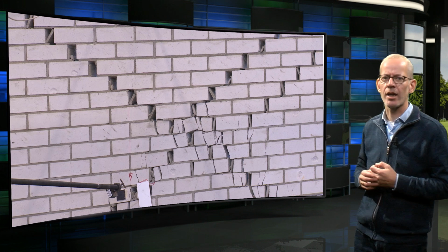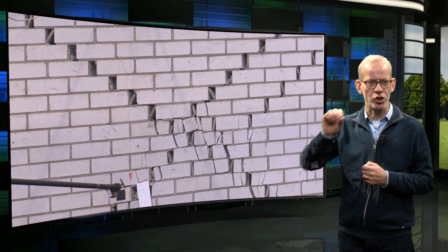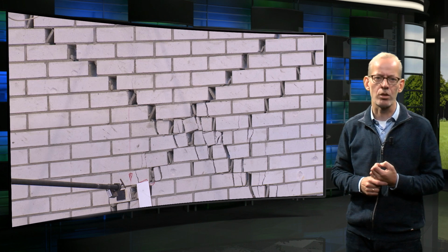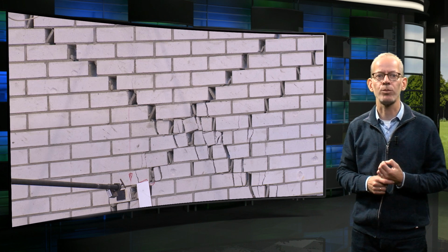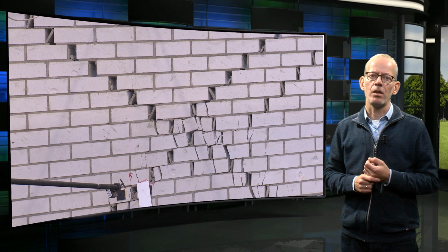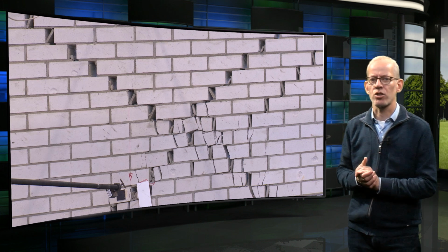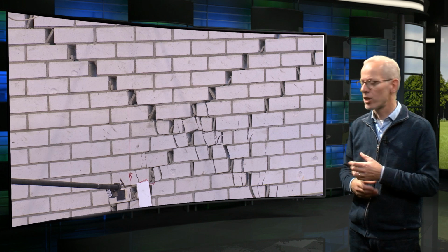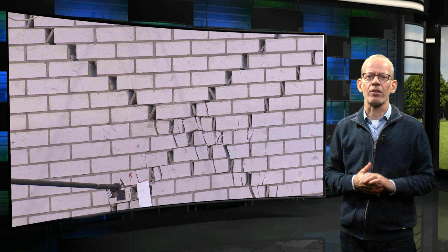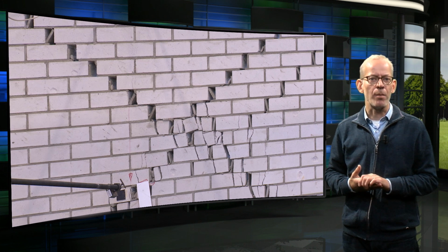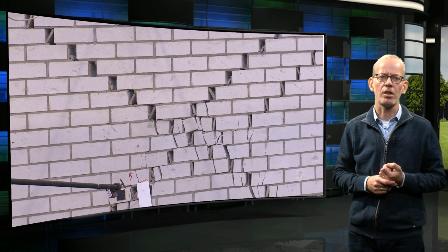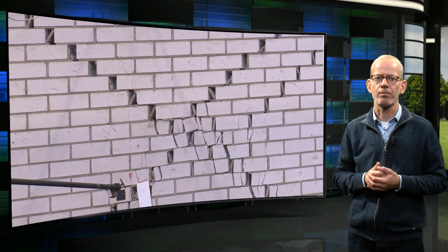You can clearly recognize here the two diagonally shaped series of cracks going from both the top left to the lower right and from the top right to the lower left. If you examine one of the cracks in more detail, you can see that the head joint has opened while the bed joint is still connected. At the same time, however, a clear horizontal shift is visible between the bricks due to the sliding action.